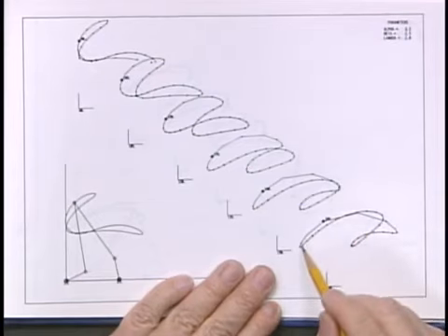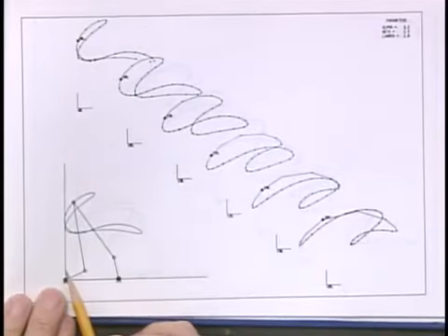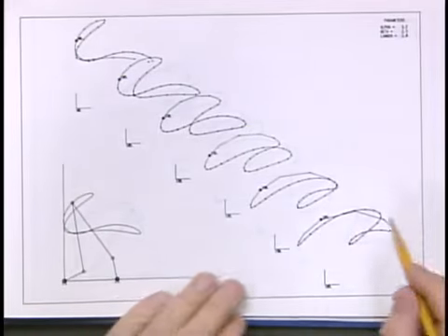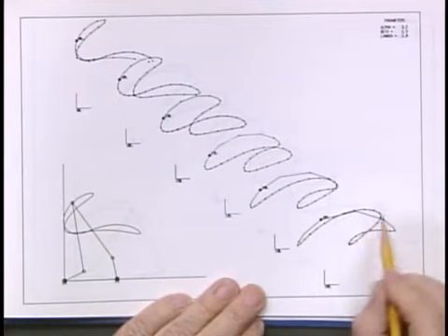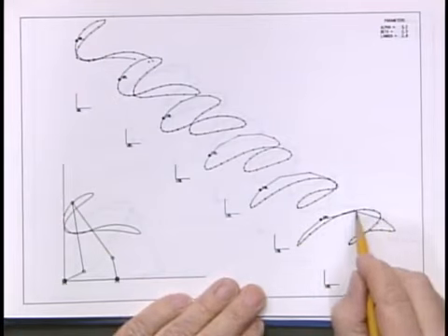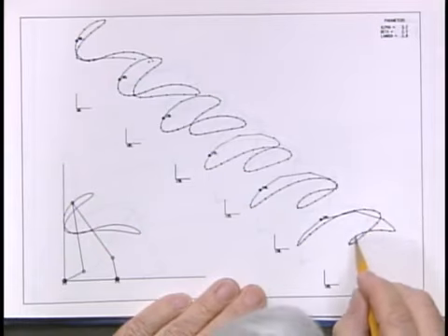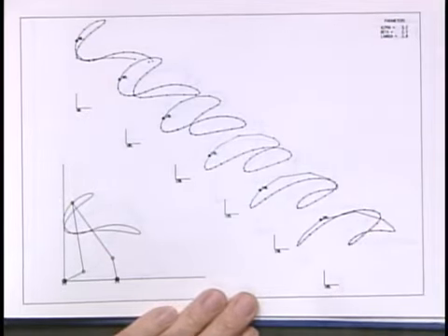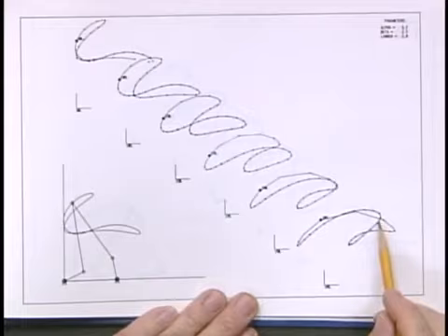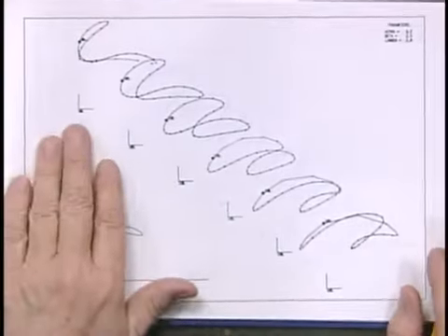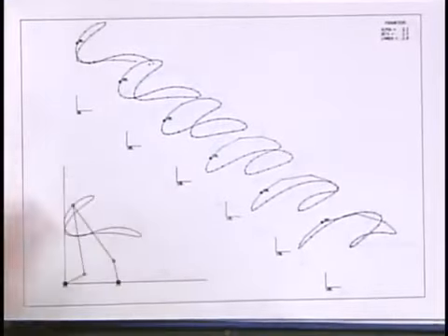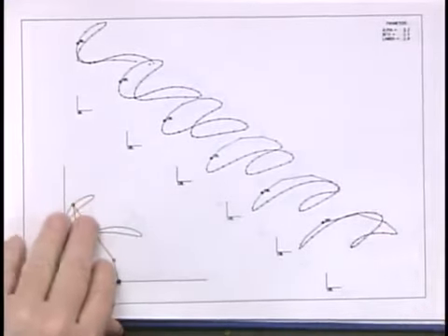Each of these dots is the same crank angle input over here, which for a constant speed input is the same delta time. So notice this is going really fast across this portion because it's going from there to there in the same time that it takes to go from there to there on this part of the curve. So there's a huge quick return ratio in this curve. So if you need some very crazy motions in your machine to pick something up and place it over here and turn it upside down or whatnot, these linkages have some potential.